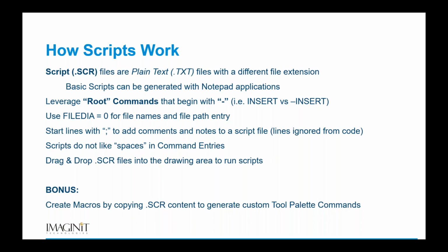The real big advantage again to scripts is it's just a drag and drop. So you don't have to load anything, you don't have to run any background commands. You can take a script that's saved on your desktop or in a folder and drag it into any AutoCAD session. And as long as the commands are recognized, it's going to work.